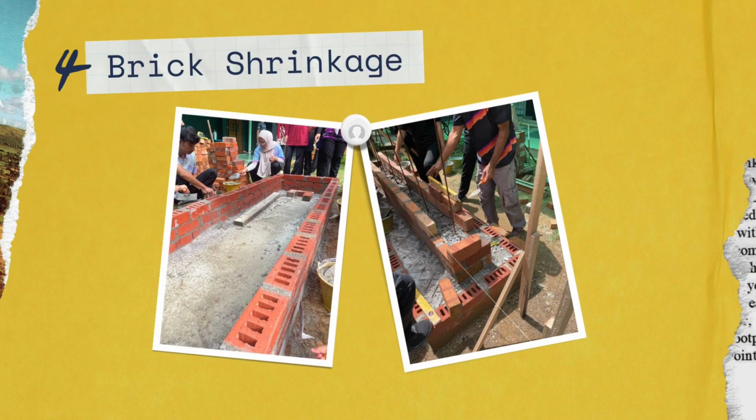The fourth one is brick arrangement. The arrangement of the bricks chosen is a stretcher bond, also known as running bond. It is a pattern used in brickwork, where bricks are laid with their long sides alongside, called the stretcher, exposed and facing upward. Each brick is staggered by half its length from the brick in the adjacent row, creating a continuous overlapping pattern.